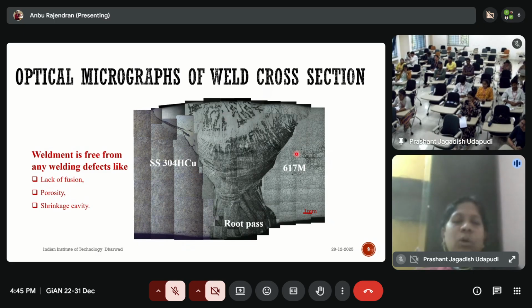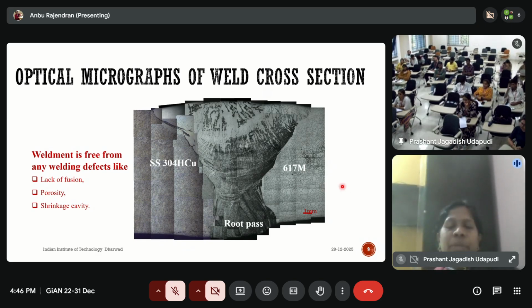So in a single click we could not cover the entire area. So we took multiple small images at the maximum possible size, then stitched all the images in the proper sequence, so we could get the detail. Okay, so this is one of the weld samples. We were looking at how the interface at the joint is, and looking for any presence of defects. Those analyses can be done by preparing the cross section of the weld.